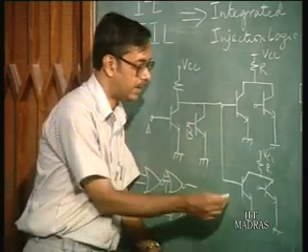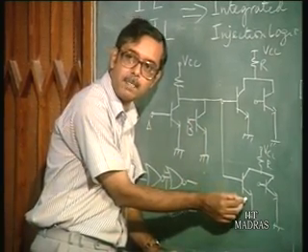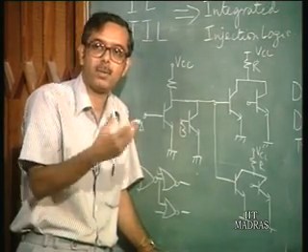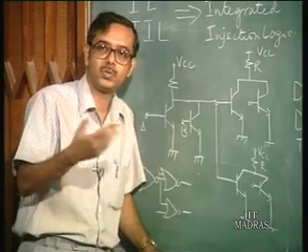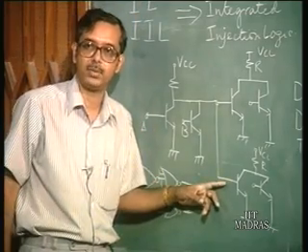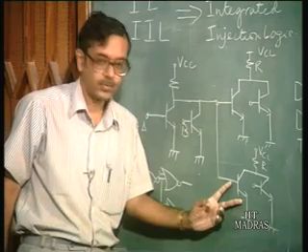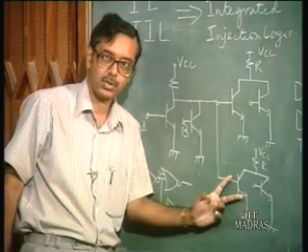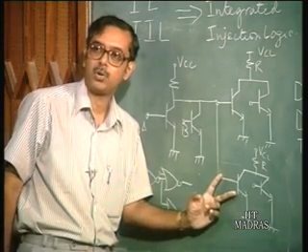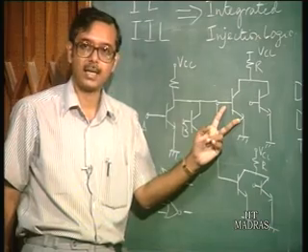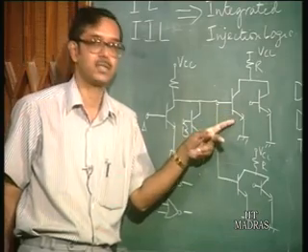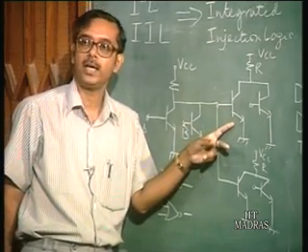When this transistor starts to conduct, suppose the difference is very, very small, maybe not even 1 volt or 2 volts. Because of the exponential nature of the IV characteristics, if this base starts conducting at a lower voltage, the voltage will become more or less clamped, and this transistor is not going to get current, because the input voltage is not going to rise to the point where it starts conducting.